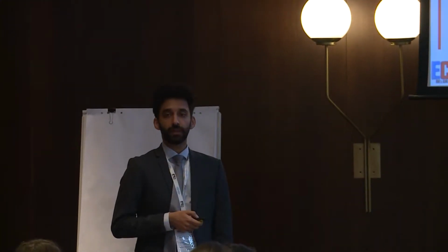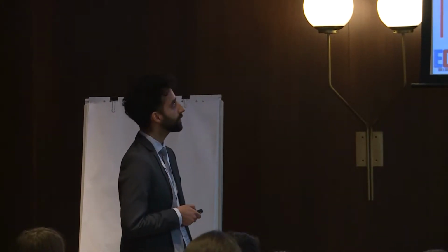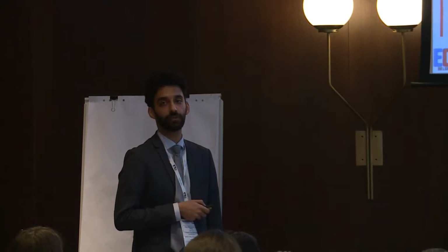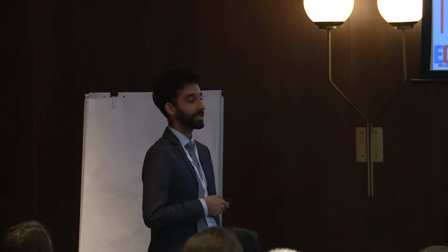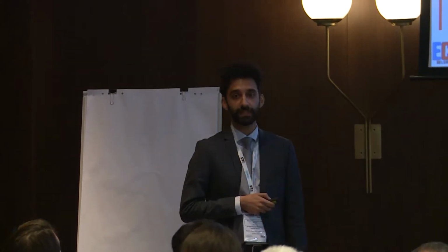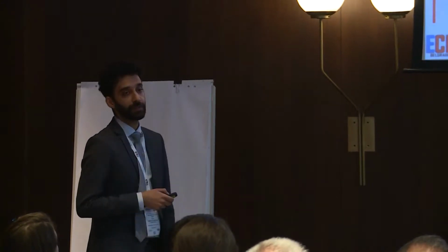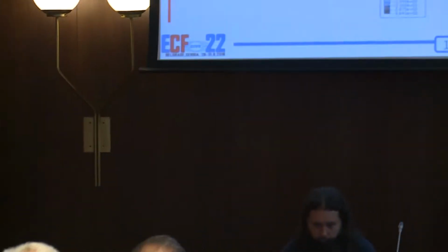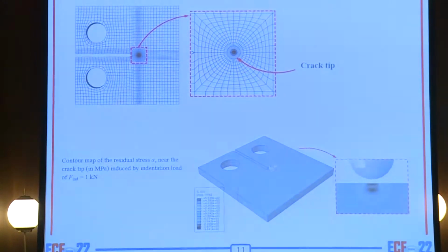Because the samples were thin, there was the chance to have buckling. So 2 plates, or it's better to say 4 plates, were used and screwed on both sides of the sample to prevent buckling during the testing, and the samples were tested under actual loading. Some finite element method models were used to capture the residual stress in front of the crack tip and along the crack line.